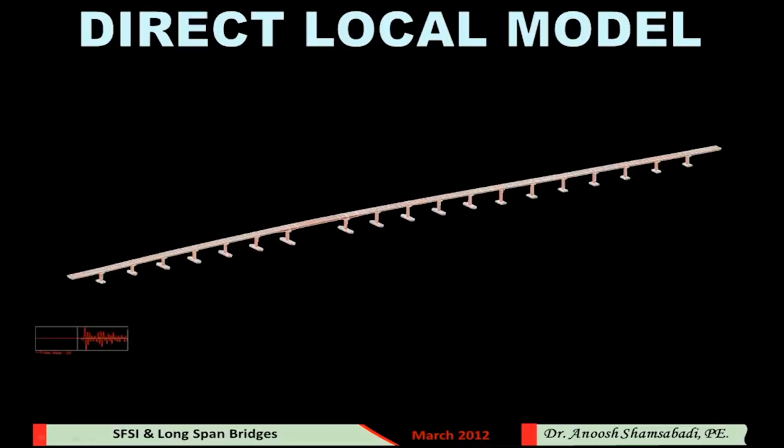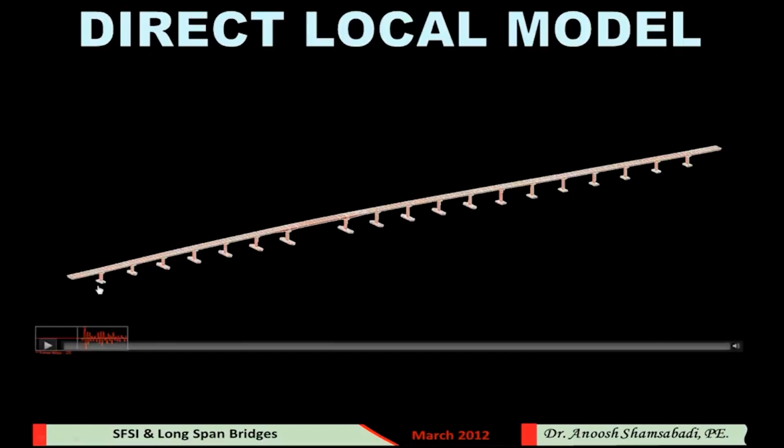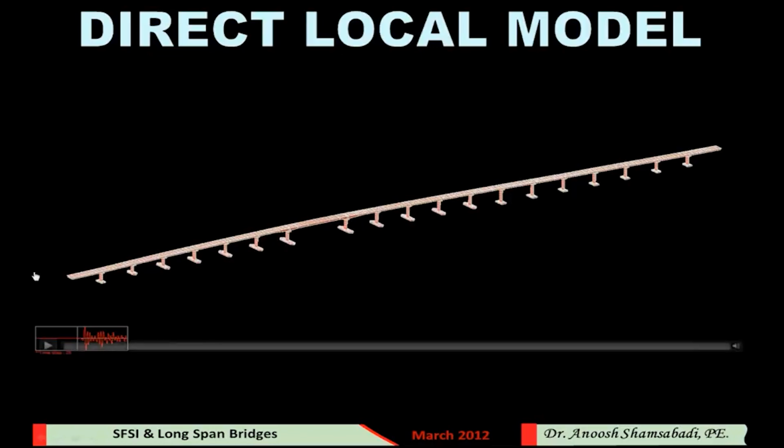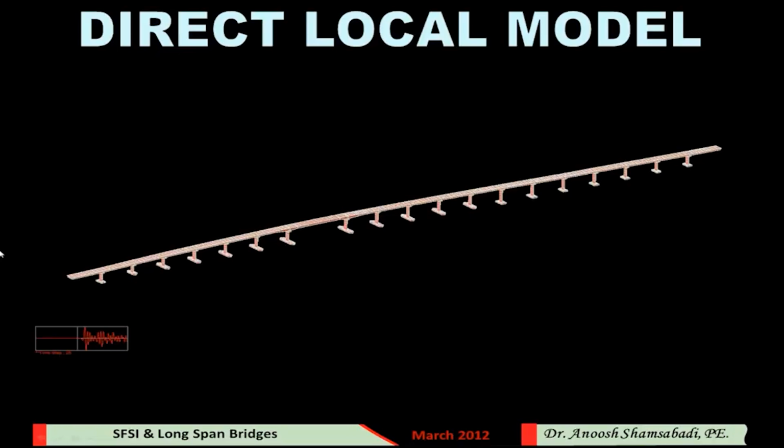Now, I developed this model yesterday. Since I had the model of the superstructure, I decided to also develop a substructure model. With the substructure model, I put a 6x6 stiffness matrix, damping matrix, and mass matrix at every location here, and shook the model to see what we're getting. I was very surprised actually.